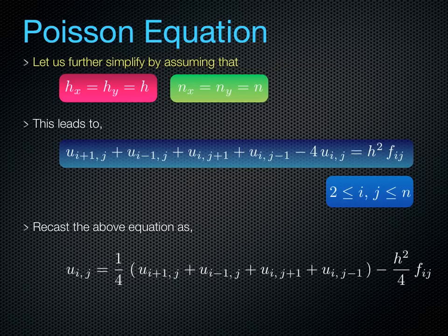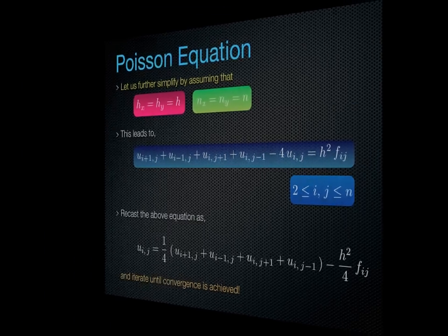And come back to the original point that we started with, and see when we repeat this procedure, whether the value of the field variable changes there. If it does change, then we keep sweeping. If it doesn't change, that means it has stabilized and converged, and that we have found the solution. So we would repeat this until convergence. I'm going to show you a MATLAB implementation of the iterative scheme, not the Gaussian scheme, which we talked about earlier, so that you can see how it works clearly.